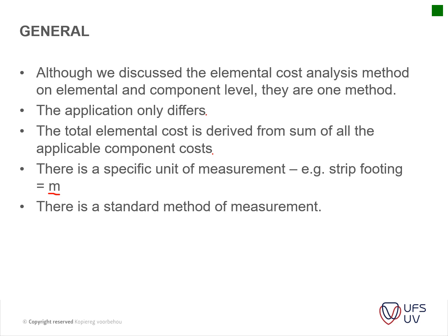So in your elemental estimation, you basically measure the length of the strip footing, but in your bills of quantities, that length of strip footing is broken down further into the different elements, like the excavations, the carting away of that material, the backfill, the blinding of the concrete that has to go in, the actual concrete that goes into the strip footing, and then the building up of the brick walls in the foundation, backfill to that again, the compaction of that, etc., etc.